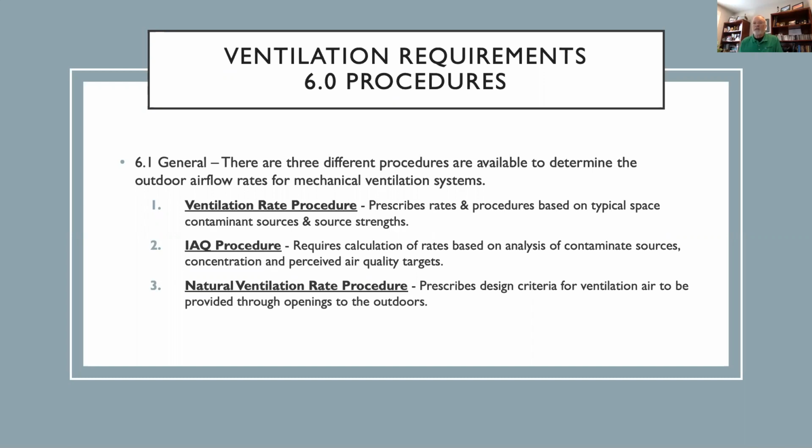The ventilation rate procedure has changed. That's what most everybody uses, and that's what I'm going to talk about. I've got one slide on the IAQ procedure that's going to give you a warning: if you think you want to use that, make sure you know what you're doing if you claim you want to comply with ASHRAE 62. And 2 or 3 slides on natural ventilation.